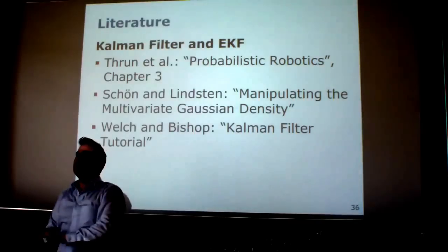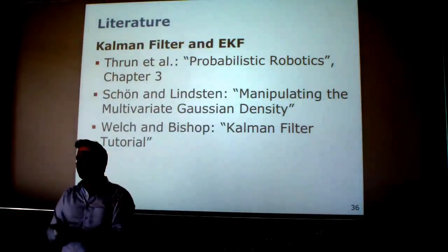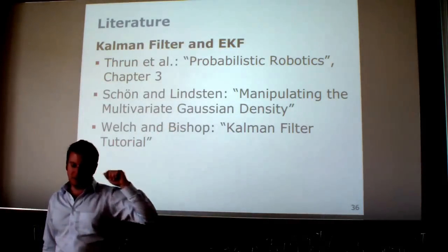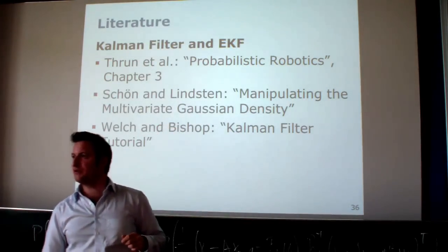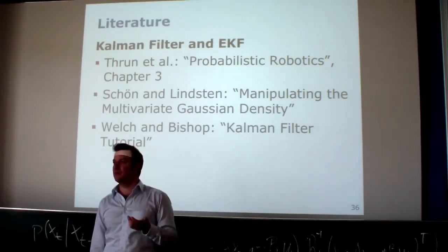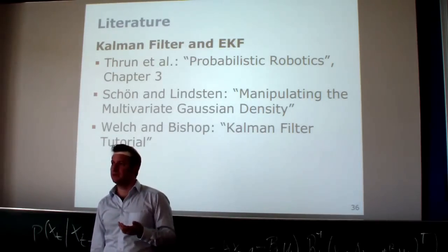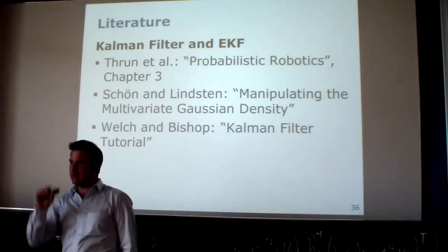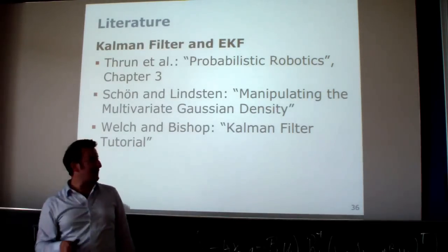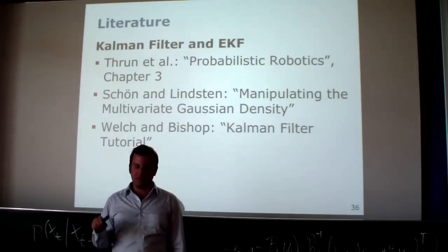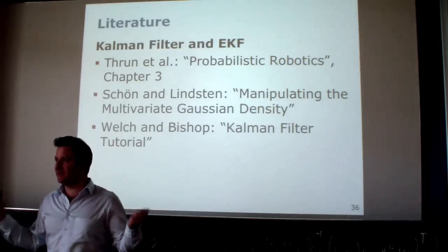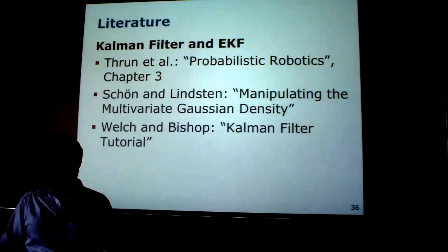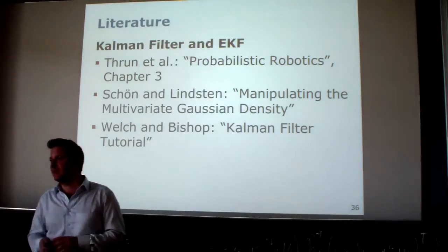So the more landmarks you experience in your world, the bigger your state vector gets. Therefore, this quadratic complexity in the number of landmarks is typically the limiting factor in the Kalman filter, because you always observe things locally. The dimensionality of your observation is typically small in most cases, so that's all fine. But the limiting factor is really the number of landmarks. It's quadratic in the number of landmarks every update step. That's the problem, at least if you go to large environments.